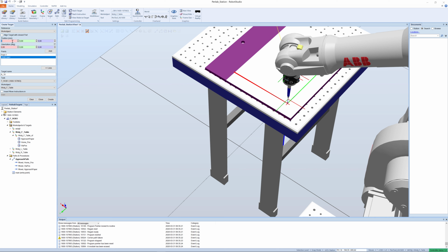The second one is at X, so we just put in 50 on the keyboard, and tab gets us the next one, 20, and click on add. Oh, sorry, this was not meant to be. I click on that one and put in rotation 180 degrees, modify, and that one, 180 degrees, modify, like that. That should be fine.